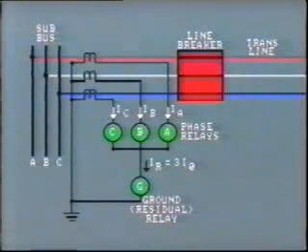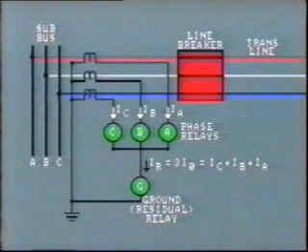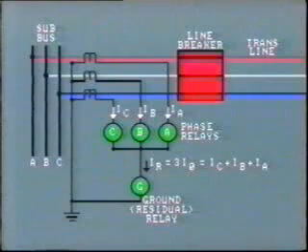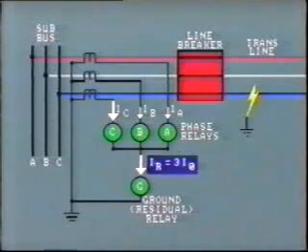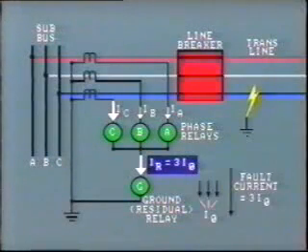As you know, the residual current, IR, is the phasor sum of the three-phase currents. Normally, it is very close to zero. But when a line-to-ground fault occurs, this current becomes very large. You will often see the residual current expressed as 3I0. Remember, the magnitude of current for a single line-to-ground fault is just 3 times its zero-sequence component.